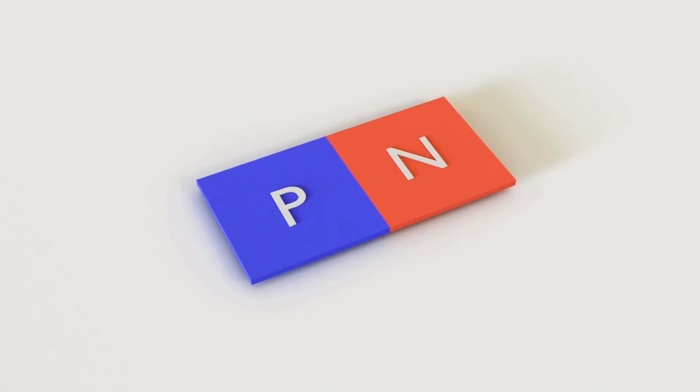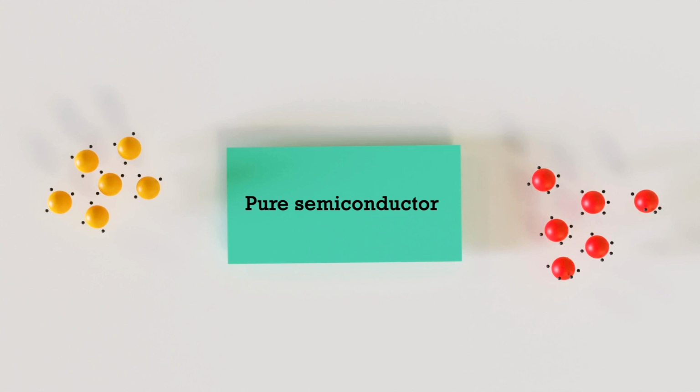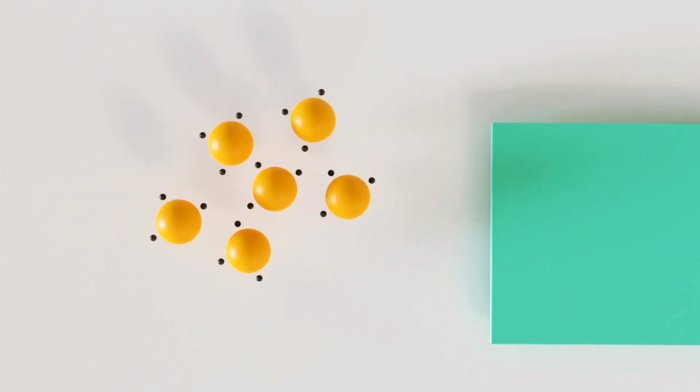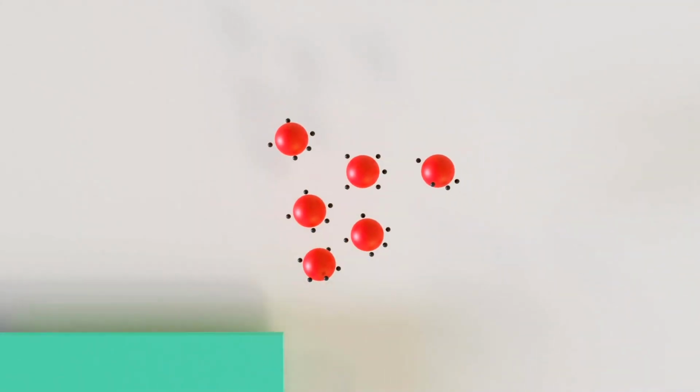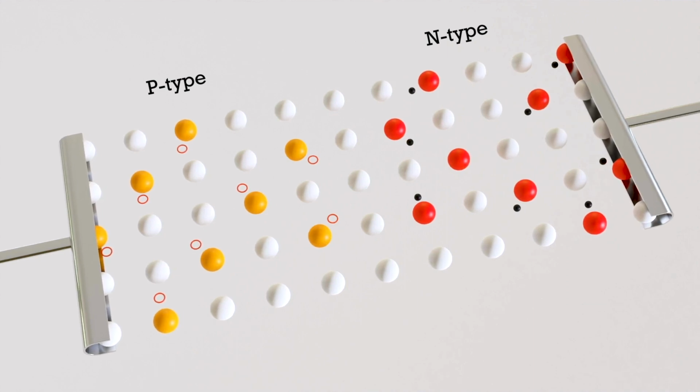Now, let's see how p and n-type semiconductors are used to construct a diode. To form a p-n junction diode, a single piece of pure semiconductor is half doped with a trivalent impurity, and the other half is doped with a pentavalent impurity. As a result, half of the material becomes a p-type semiconductor, and the other half becomes an n-type semiconductor. Let's see what happens in a diode at the atomic level.